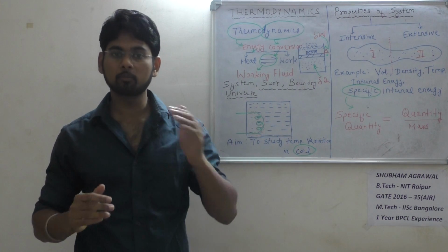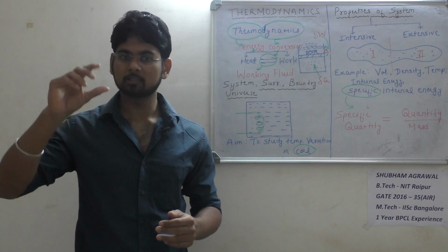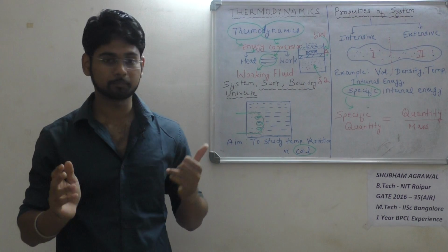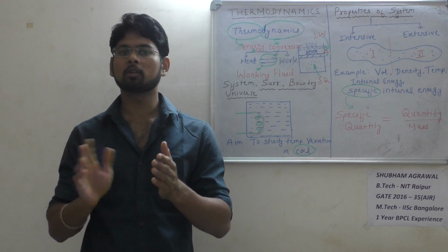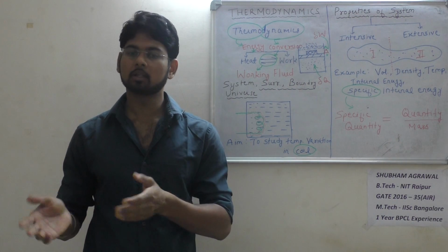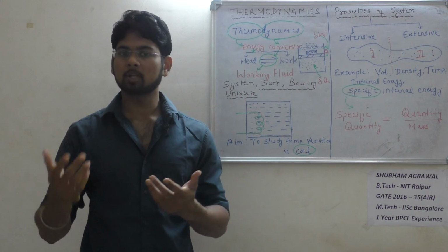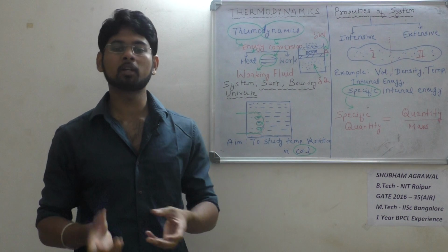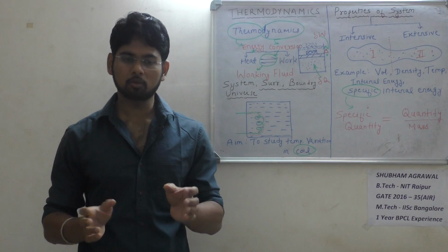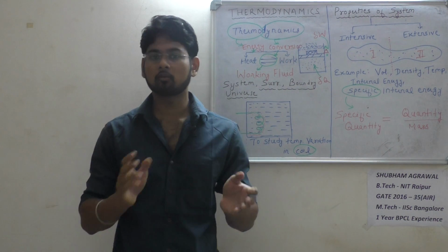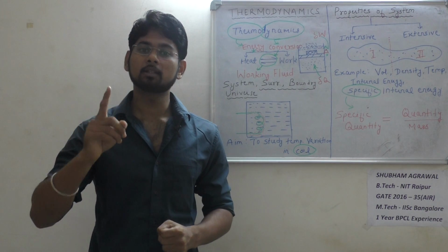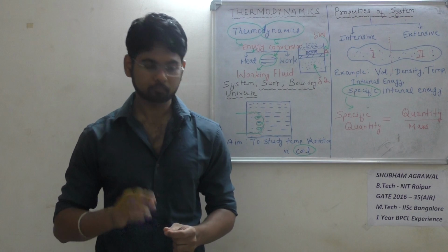So the heat input del Q that I have given produced the displacement delta, which represents del W, the work in the experiment, right? So this is how the conversion of heat energy to work energy takes place, right? In a similar way, if I compress the piston in the opposite direction, the same amount of heat will get rejected. So in this way we can convert heat energy into work energy and work energy into heat energy. The condition is that the fluid must be compressible.